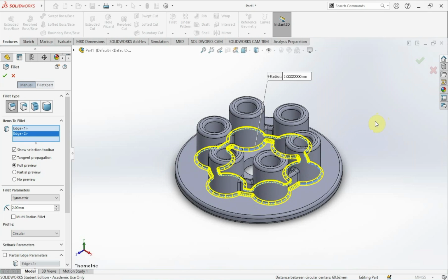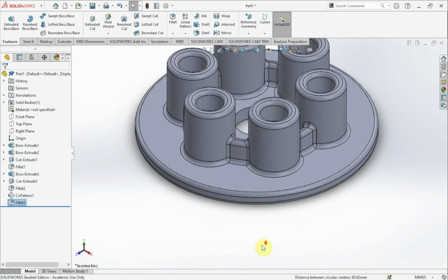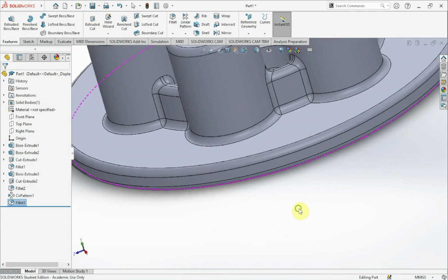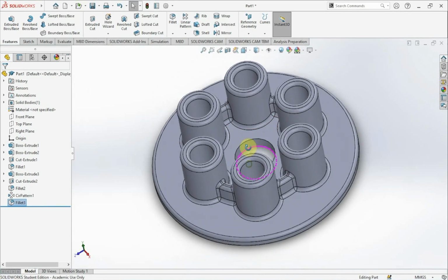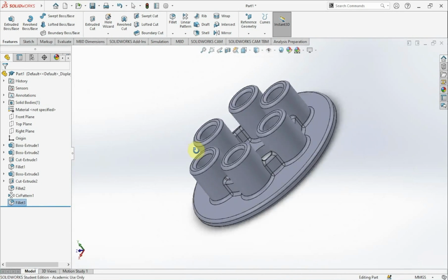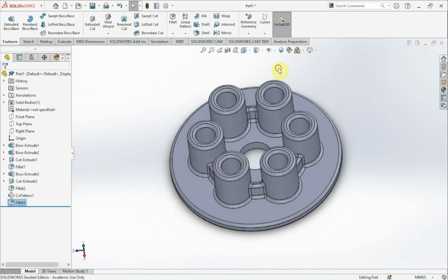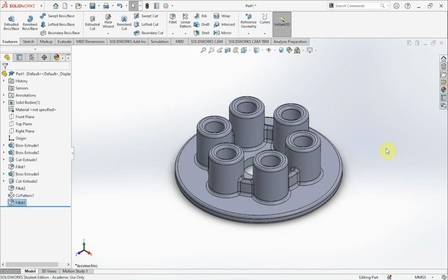Once you use circular pattern, if we use it on the host, let's just call it that, a host, then it's going to make it on the other copies. Just go ahead and click on OK. And there we go. We get those rounded edges once again, on the inside and on the outside. And there you go. That's basically it.